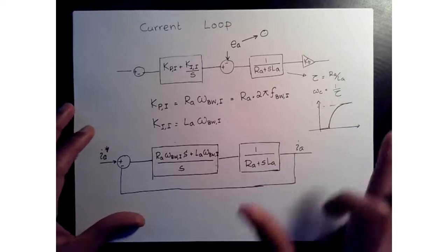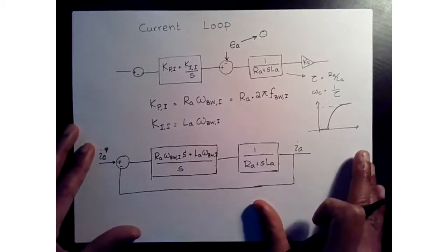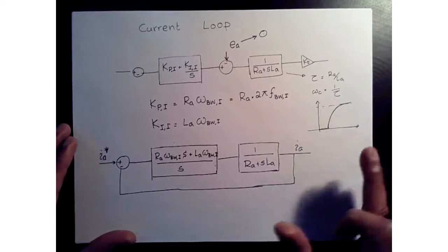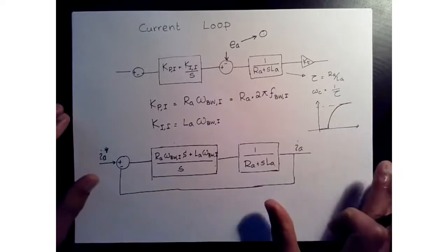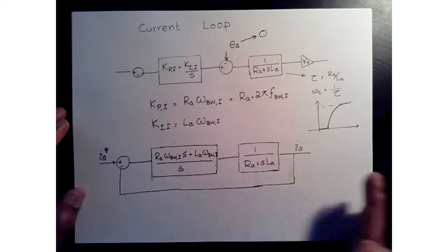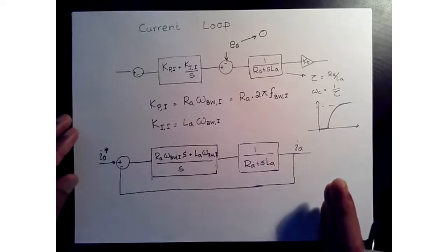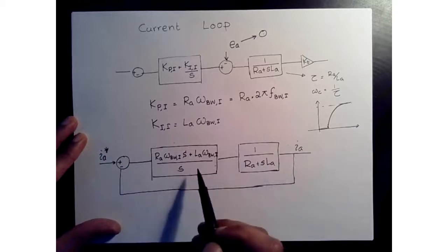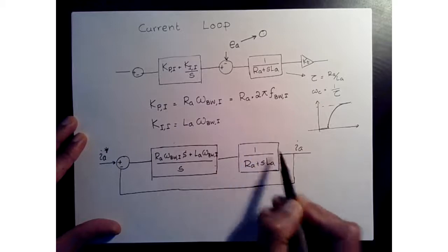Now you have to be very careful. This is a balance that we have to strike when you do a system design. You don't want a very high bandwidth because now you're going to have noise influencing your system. You might see unintended actuation, some vibration passing through the system, if you have too much bandwidth. So always select your bandwidth in a reasonable manner. And the cool thing is, with this configuration, we can now change the plant characteristics. You'll see what will happen.